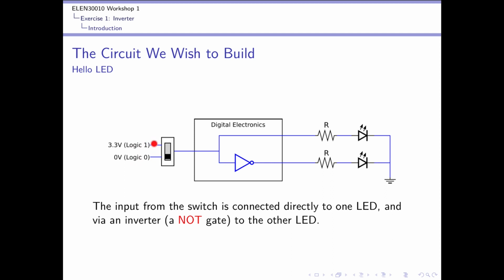Remember, in digital logic, we can think in terms of 0s and 1s, or off and on, or low and high. They're just different ways of describing the two voltage levels. Low is 0 volts, and high is, in this case, 3.3 volts. So in terms of voltages, because at the end of the day, this is just made using transistors, and we'll learn how later.